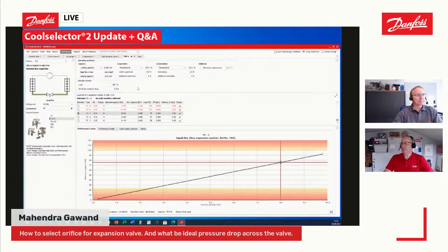However, there are a few points, and I think Mahendra is pointing to that one. Usually the evaporation temperature, talking about a refrigeration system, is given. So this is fixed, but the condensation temperature may vary due to seasonal conditions. This is one variable value, and the other one is often underestimated, the distributor pressure drop.